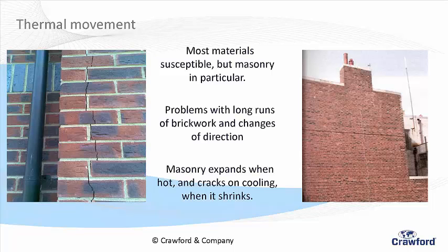And this one here is actually fire damage. So can you see the smoke there? This is actually a fire claim. But I was interested in it because although it's a fire claim, the temperatures internally were quite significant. Externally, you just spotted that this wall had expanded there and cracked along an internal cross wall where it had been keyed. It's thermal cracking, nothing to do with foundations. That would be covered under fire, obviously. That's not covered. Any thermal cracking, you can imagine plaster cracking, masonry cracking, concrete cracking, not covered.